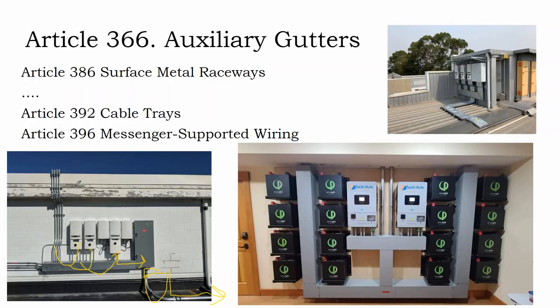And so what the gutters do is allow you to grossly simplify all your cabling coming in and out of the various conduit runs. And it also gives you these nice, straight, little short stubs between one section and the next, so that you don't have to deal with all the complicated bends and parts and fittings. But this sort of stuff is best pre-designed.